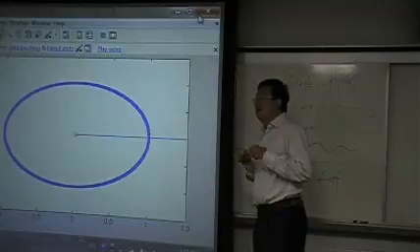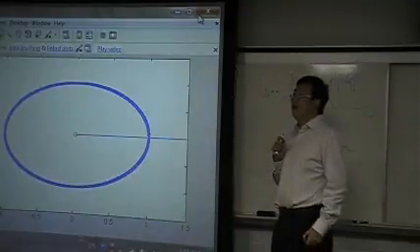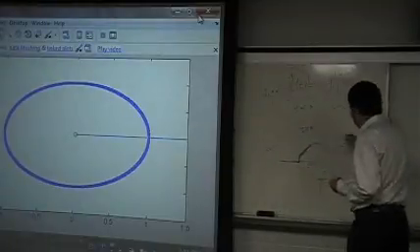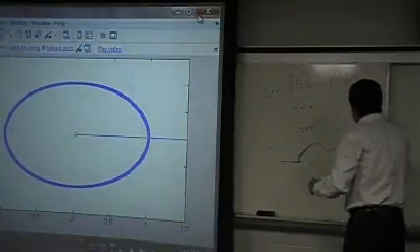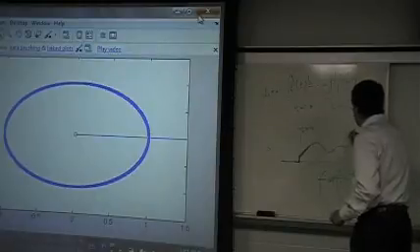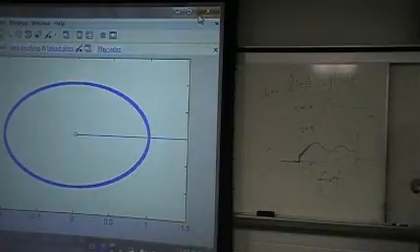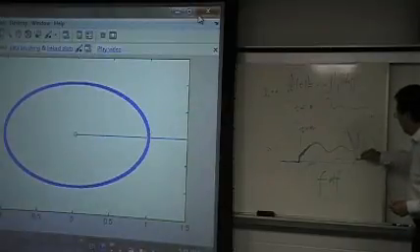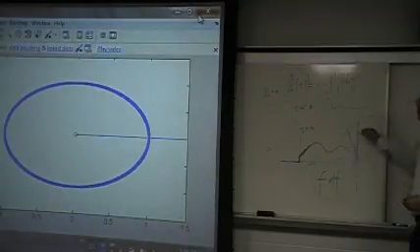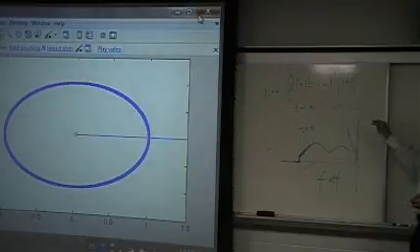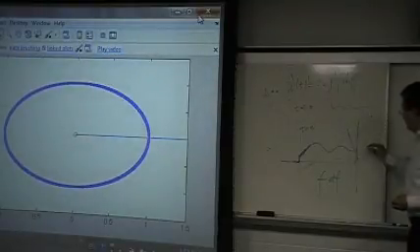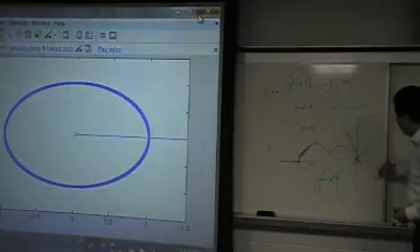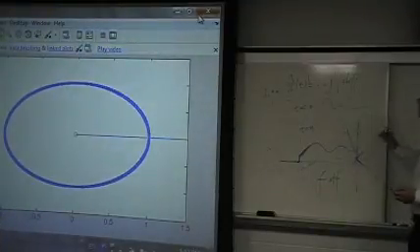Yeah. If alpha is smaller than 1, the stable region is bigger. If alpha is larger than 1, the stability region is like this. Right? For the integer order system, if alpha equals 1, it is the vertical line, the y-axis. So for alpha smaller than 1, the unstable region should be smaller.